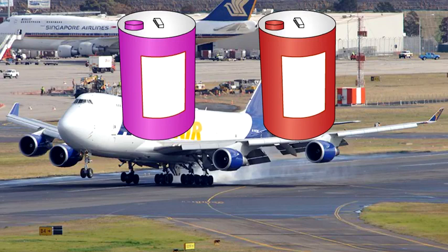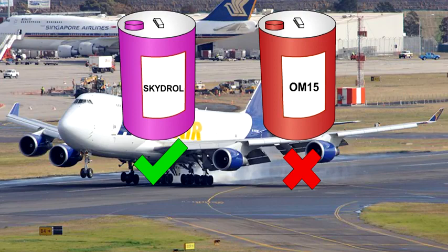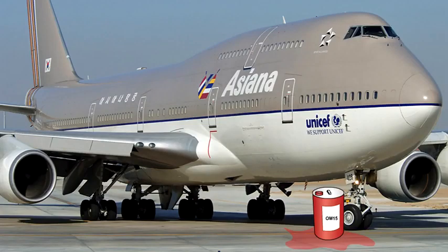It is of major importance that only the specified hydraulic fluid, or its approved alternative, is used in a hydraulic system. If the incorrect fluid is added to a system, breakdown of the seals is likely, causing fluid leakage, both internally within components and externally from the actuators. Failure of the seals in the pump could well lead to overheating. Filters may become blocked with debris, and parts may be damaged by corrosion.